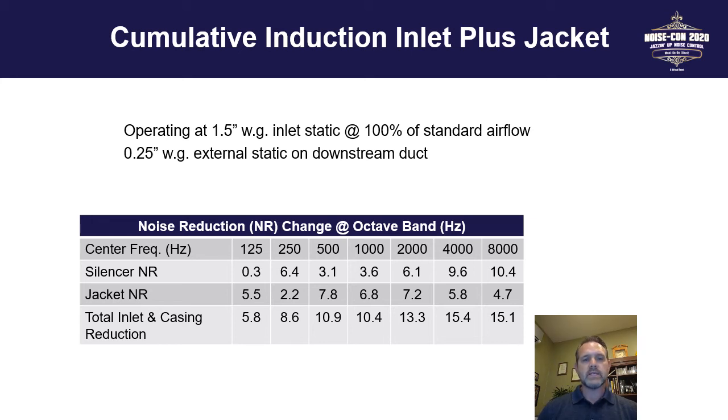So the first pass, we took a silencer, mounted it to the inlet of the induction inlet, and you can see the performance there in the first row. Not real great in the lower frequency bands, and then certainly increases as we go up in frequency.